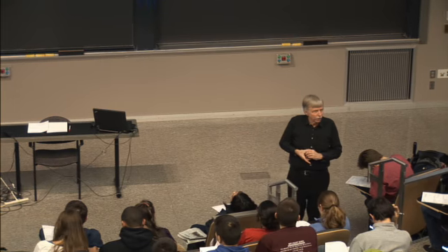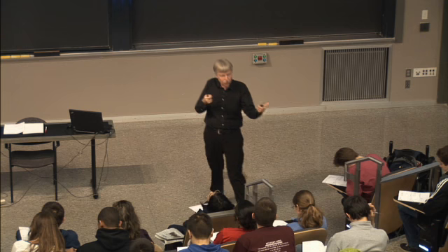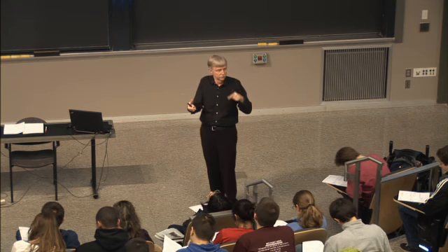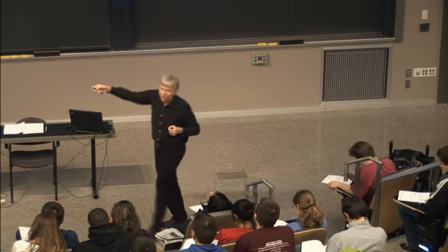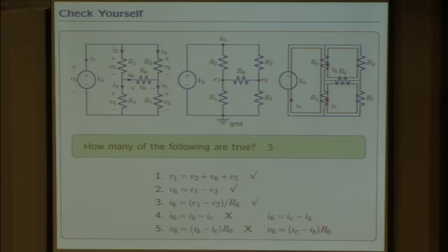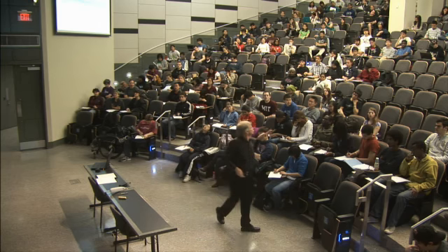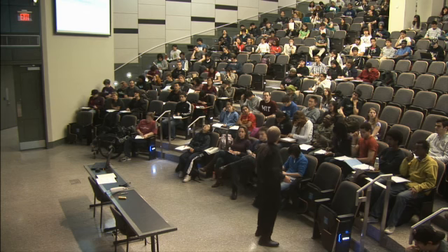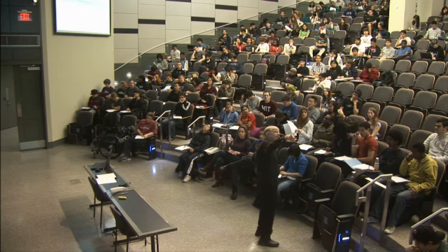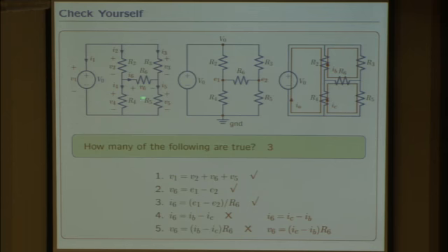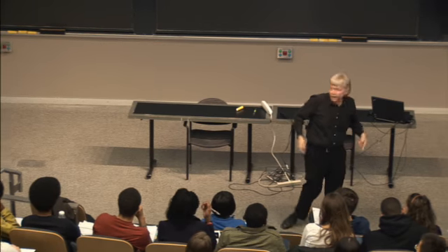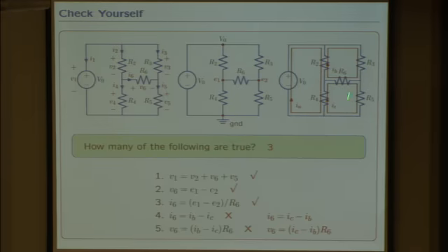So equation 4 is the relation between element currents and loop currents. So what's equation 5? Equation 5 is Ohm's law for loop currents. Ohm's law, again, if I were thinking about Ohm's law for R6, I would have V6 equals I6 R6. That's the way you say it in element voltages and currents. Over here, the current through R6 is IC minus IB. So Ohm's law looks a little bit more complicated.